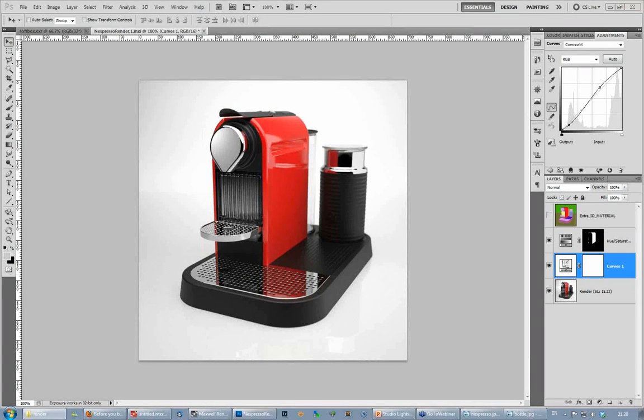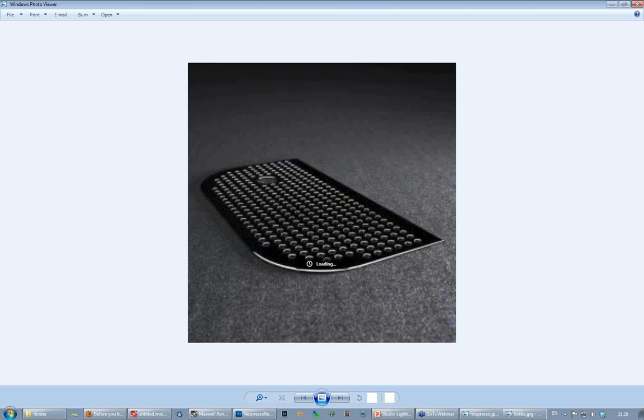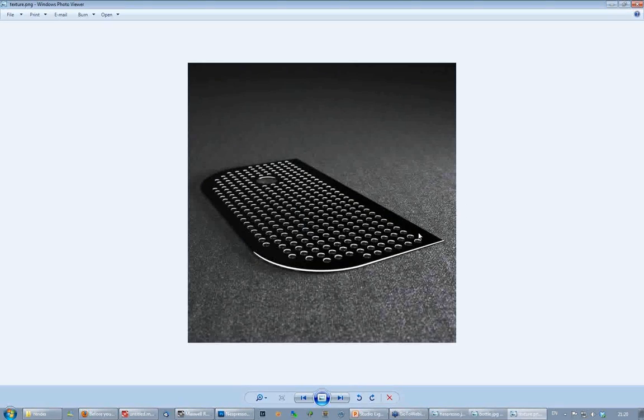So you can't do the stuff like, for example, in this case, I just added an emitter close to this object, and I have more light control because I can control the placement of the lights depending on the distance of the object. If you're using something like HDR Light Studio, because it's an HDR, so it's a huge sphere around your scene, you can't control really the light by this light falloff and the distance from the light to the object.